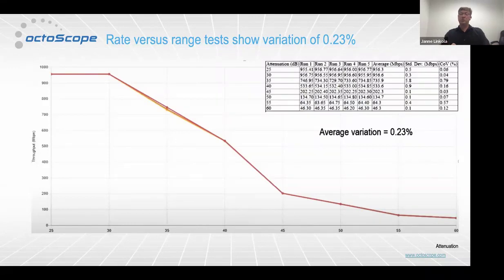But what we do is we attenuate the air link using 5 dB steps along that throughput test. I think the step was 10 seconds in this particular case. And what's happening is as the link budget changes during the test, the MAC layers of the 2 radios adapt to that change.